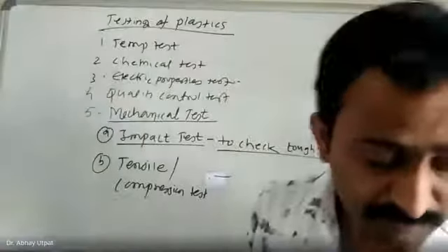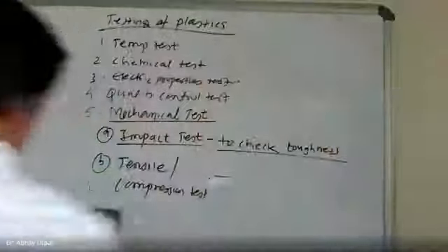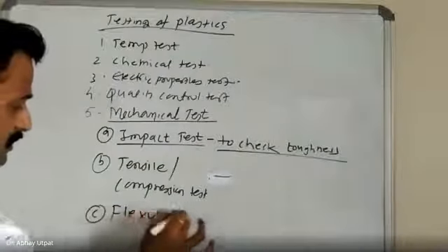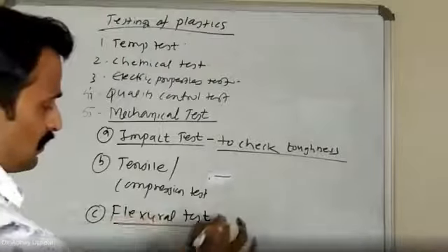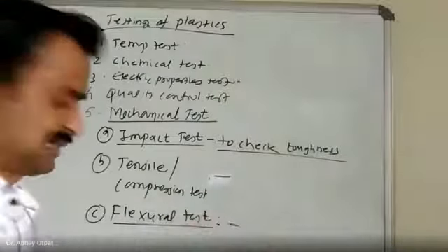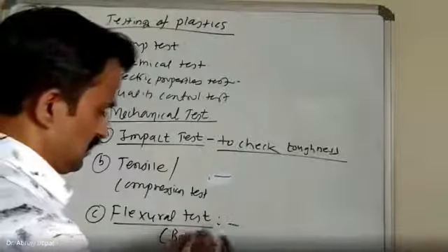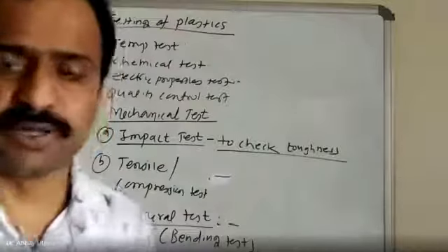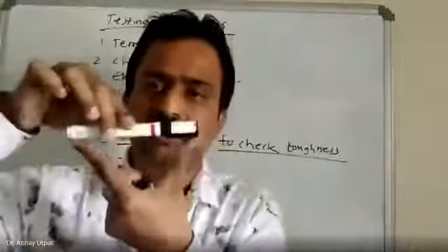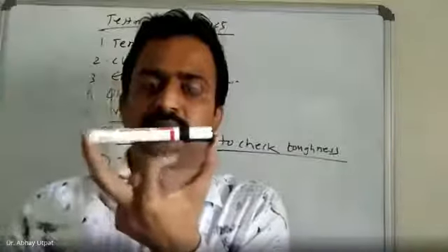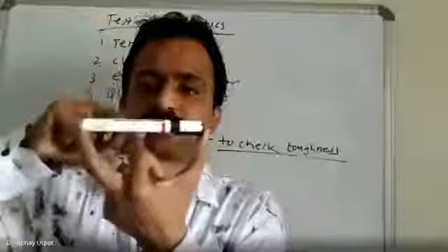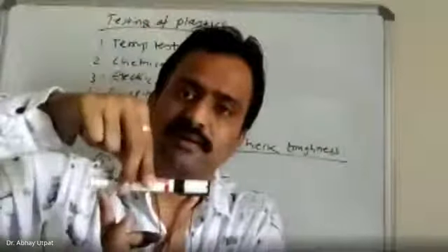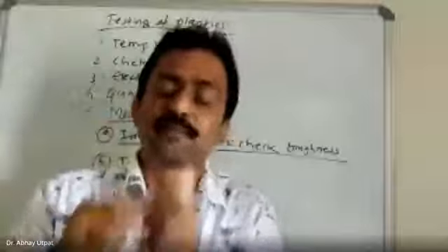Then the next one is the flexural test. It is nothing but a bending test. The part is held on two supports as a simply supported part, and then load is applied. How much maximum load can it sustain before complete bending?